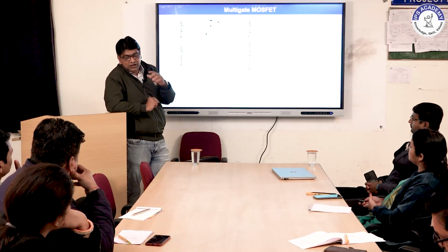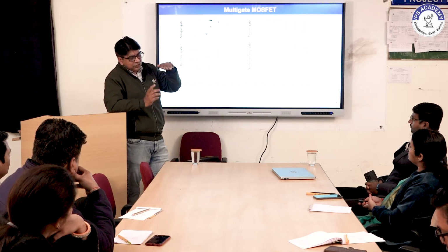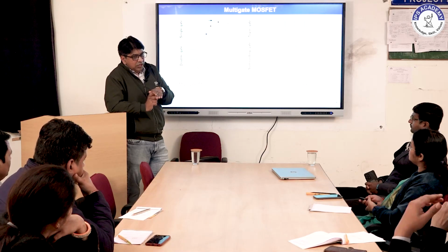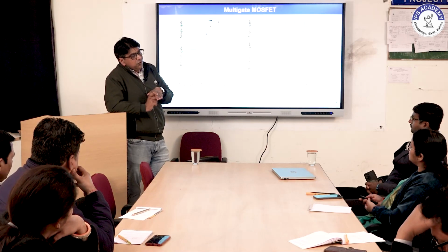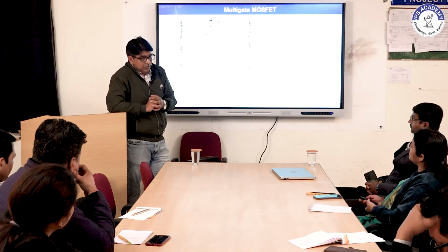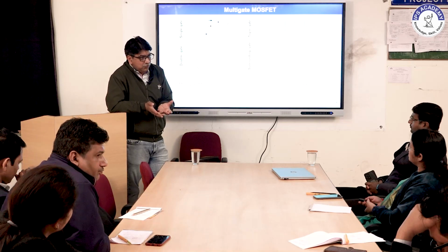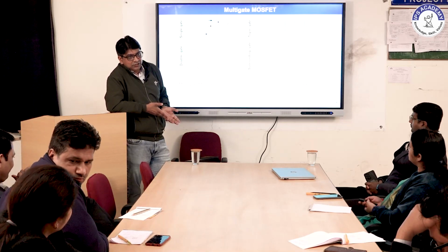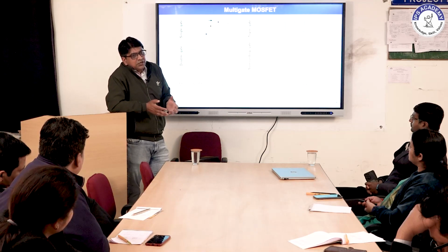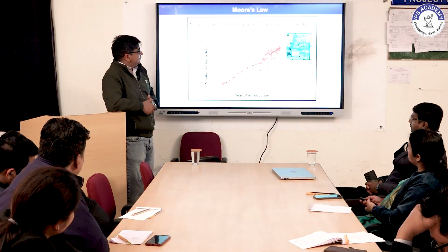The extension region will always use spacers. Spacers means at the extension length we put some other dielectric. So a high-K dielectric we use at the spacers will reduce the resistance but increase the capacitance. So again, device performance will be an issue, but it will improve your short channel effects and increase your current capability. So there is a trade-off between these, and we have to maintain the trade-off also. Come to the next slide.